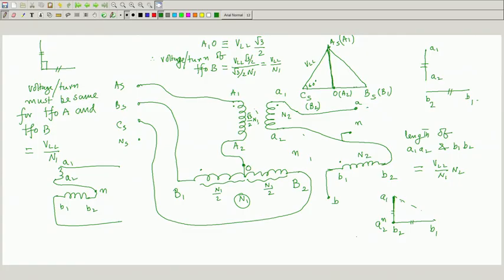So, these two transformers in terms of number of turns are not identical. Secondary turns must be the same, N2 N2, but the primary turns of transformer A, which is just drawn vertically. This vertical drawing has nothing to do with really a 90 degree axis, no. On the table you draw, I have drawn it so that I understand these phasors much more easily.